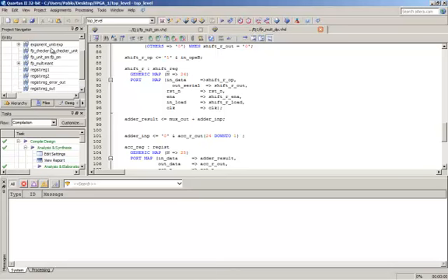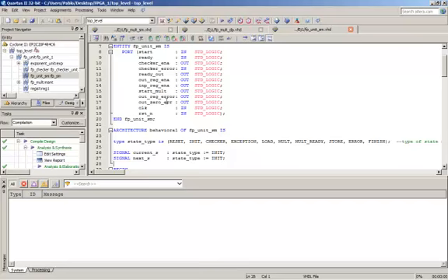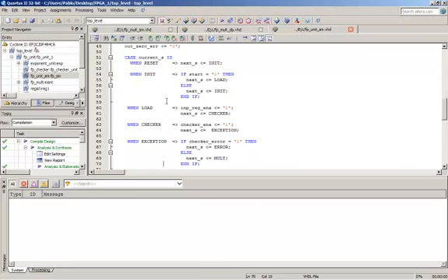If we check the top level, or the floating point unit level, we have another state machine. This state machine controls all the flow of information along the data path. It is easy. When we receive the start signal from outside, from a push button, we jump to the load state.